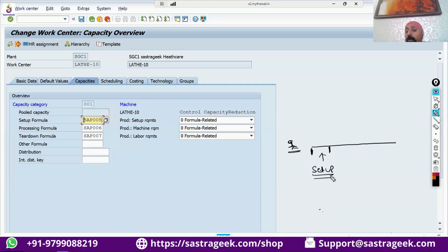What kind of setups do you need to do? You need to put jigs, you need to put fixtures, you need to set the parameters, you might need to clean the machines, remove some things and add some things. He might need to rinse the machine. If a drum was used for another chemical, he needs to push in water, rinse it, clean it, and make it dry so that it is available. That is called the setup time.